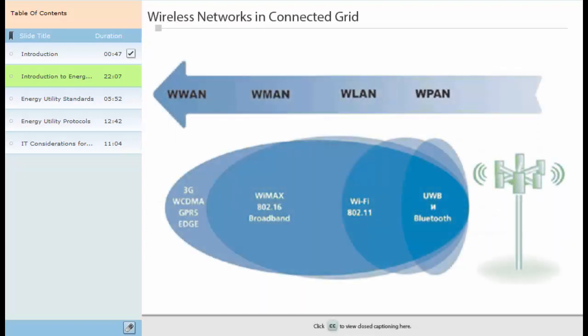Due to the large geographical area that electrical grids cover, one challenge with introducing an Ethernet-based communication system is the gaps within the networks. Based on how large the gap is, there are several wireless solutions that help support enterprise-wide networks. These solutions would include a WPAN, or IEEE 802.15.4G, a wireless personal area network, which enables one-to-one radio frequency communication between devices that are close in proximity, such as Bluetooth devices. In a utility grid, industrial routers such as Cisco IR500 enable a WPAN solution.